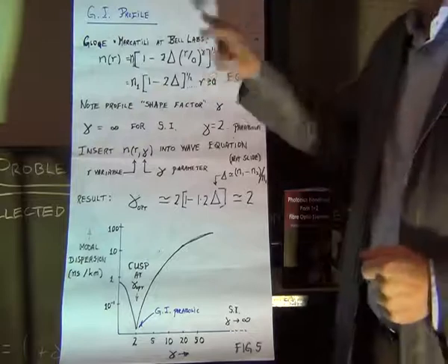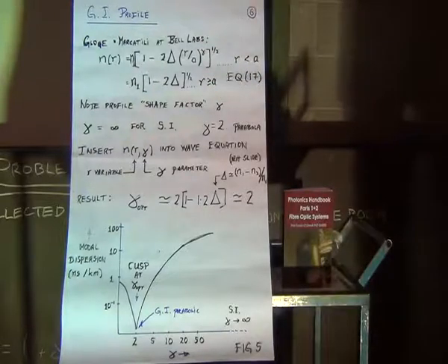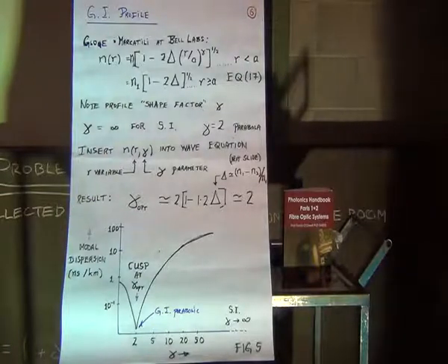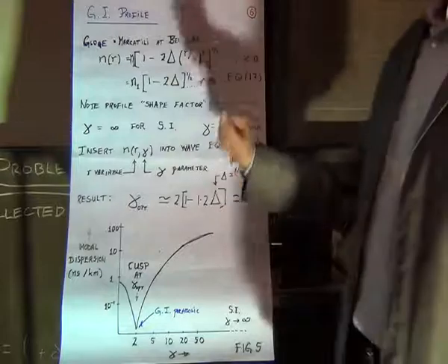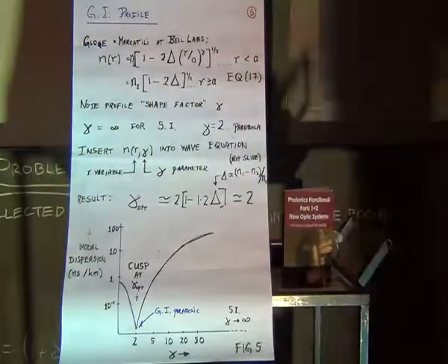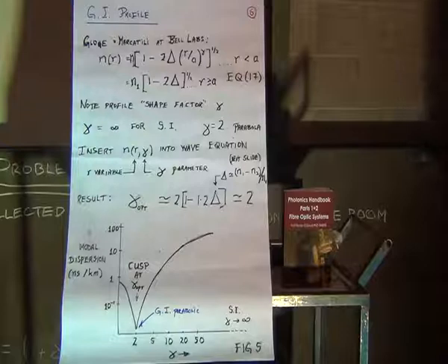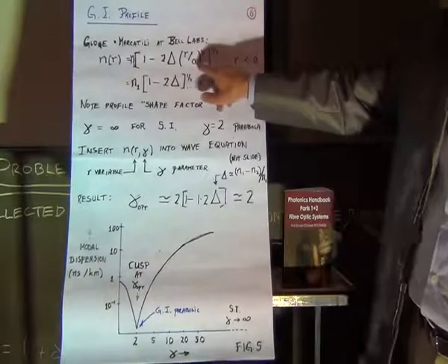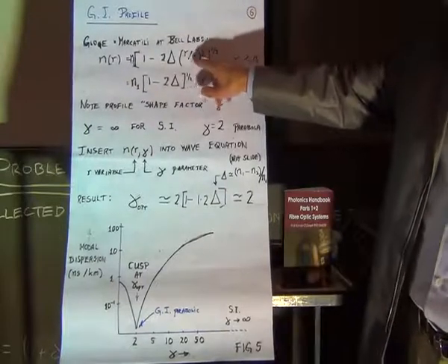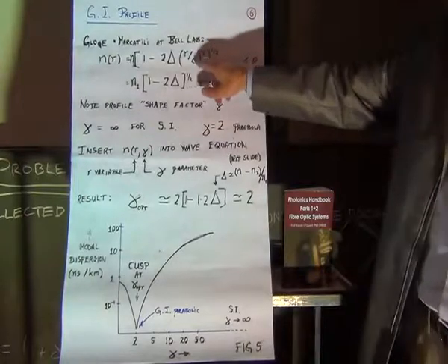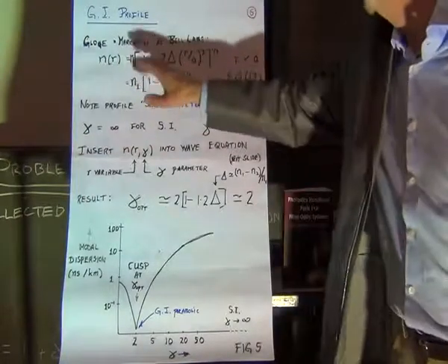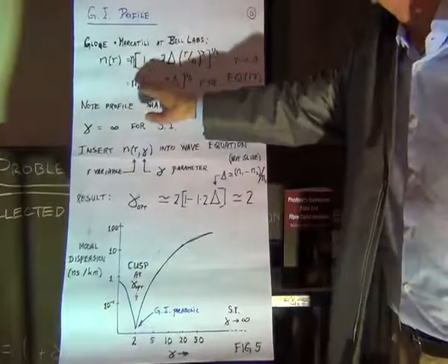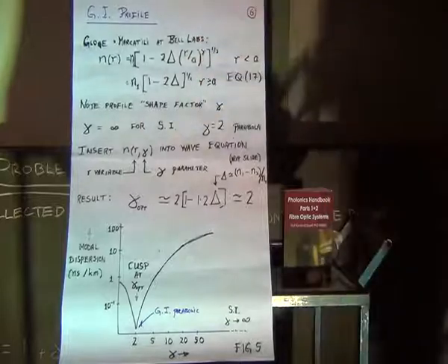They called gamma the shape factor. It's the refractive index profile shape factor. How fast is the gradation of the profile falling away? If you put gamma equal to infinity in that, you get a step index fibre. You can see that if you just look at it. No matter what r is relative to a, it's going to be a fraction, and any fraction to the power of infinity is 0. Right? So it's just going to be n1 in the core, and then n1 minus this amount in the cladding.